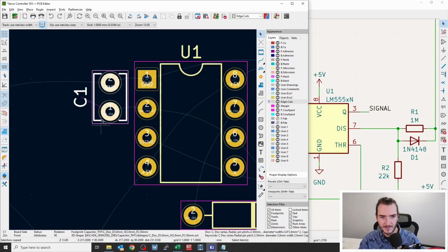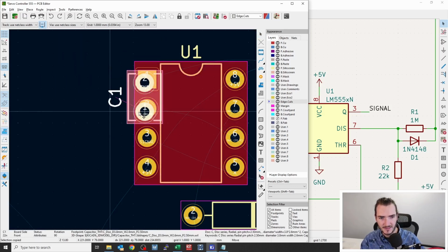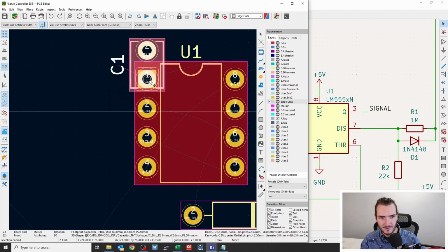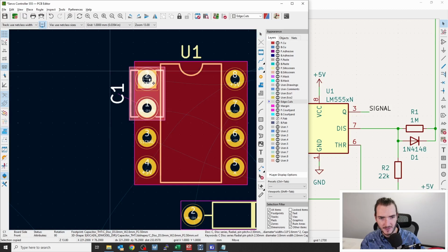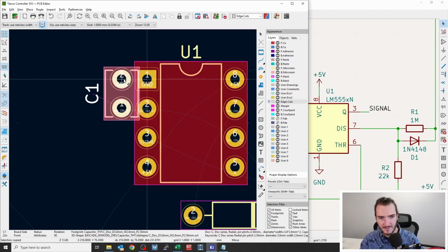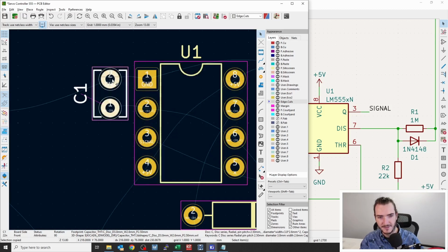Or you can just drag the component by one of its pins and line it up over the top of the part in question. Then you can strike M and just arrow key to the left, and now you've got this perfect alignment, so these connections can just go straight across. So in that way you can work outside the snapping limitations of the grid on a case-by-case basis.